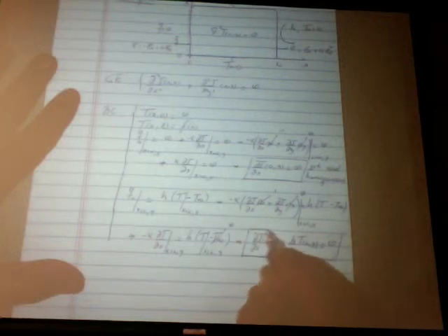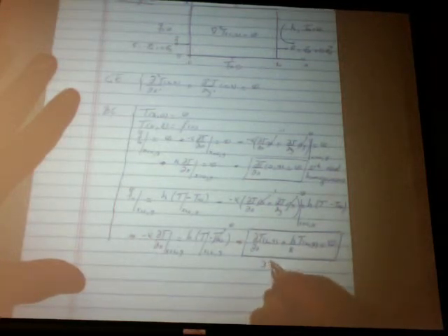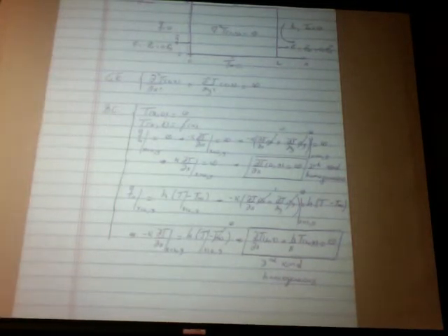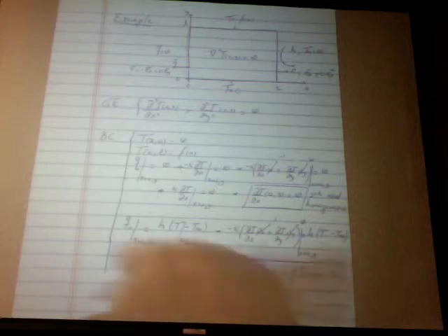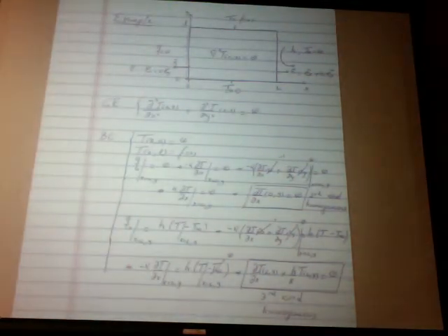And that's how we construct the third kind boundary condition. So this is third kind, and it's homogeneous as well. There's nothing on the right-hand side. If T infinity was a number different than 0, then what's on the right-hand side makes it non-homogeneous. So that doesn't drive the problem. The only thing that drives the problem are non-homogeneities. In this case, the only thing driving this problem is that condition on the top.